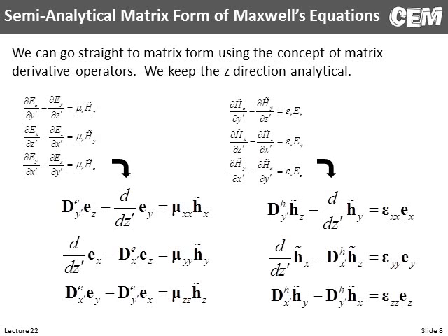And as you recall from finite difference method and finite difference frequency domain discussions, we have these lowercase letters. So H, this will be a column vector containing all the x components of the magnetic field. Likewise, this bold E, this is a column vector containing all the y components of the electric field, and so on. And of course, here's our derivative operators. These are banded matrices that calculate derivatives across a Yee grid, so we'll be adopting the Yee grid here as well.